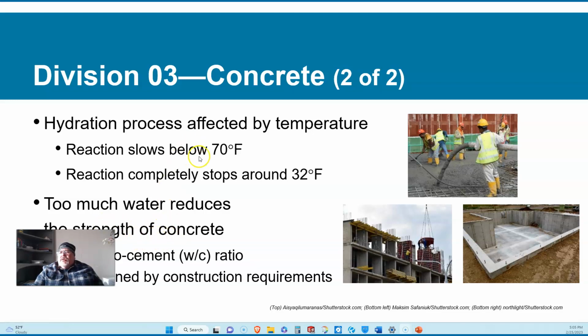So once concrete has become active and it starts to harden, and you think adding water will extend that, you won't slow down its process. Once it starts to harden, it's going to harden. You adding water is only reducing the strength and affecting the quality of your concrete. You'll actually ruin the concrete by adding water to it.